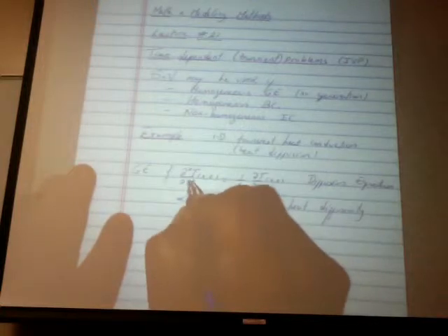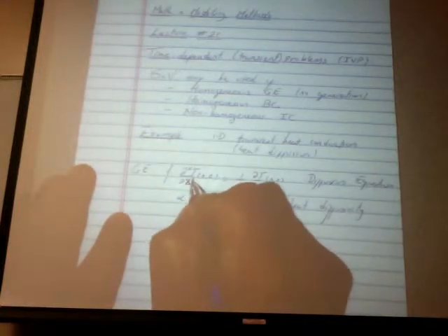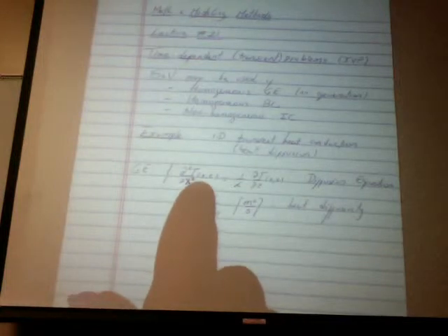and all you're left with, oh my bad here, this should be x squared. You have space squared over time. That's what the diffusivity coefficient is. So in the case of mass diffusion, it's called D. In the case of momentum diffusivity in fluids, it's called nu, or sometimes called kinematic viscosity. That also has a unit of meters squared per second.